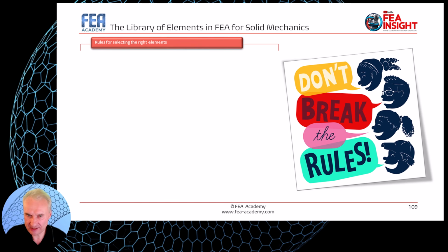Prior to defining the mesh density, you must define the element types you will use to solve your problem. At the beginning of the meshing process, it is important to know whether the structure you wish to model should be considered as a shell type or a full 3D type in order to capture the right behavior and local effects, as well as the distribution of the structure's internal loads.